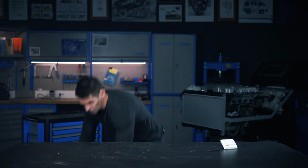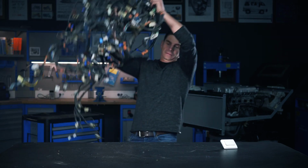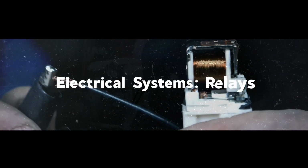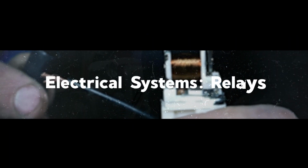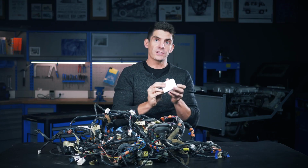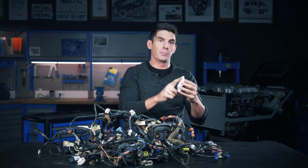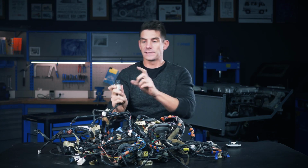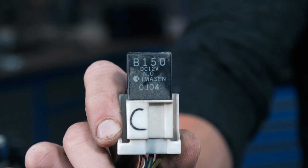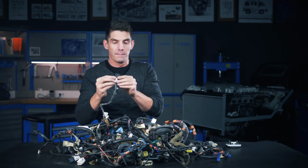Today we're talking relays. Let me wrestle this wiring loom on here and find a relay. So this is a relay and it's essentially just a switch. This is a switch. This switch is activated by your finger. A relay is a switch which is activated by a small current. So it uses a small current to control a bigger current.